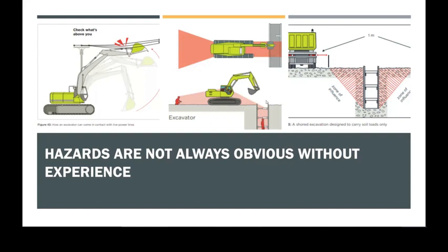And you might be his spotter, so you want to stay line of sight with him so he can see you from his cab, but you're staying just beyond, like a meter beyond his boom reach, so he can't knock you out. If you get a half a ton digger boom whacked into you, he doesn't feel it, but it can kill you, could certainly seriously injure you.